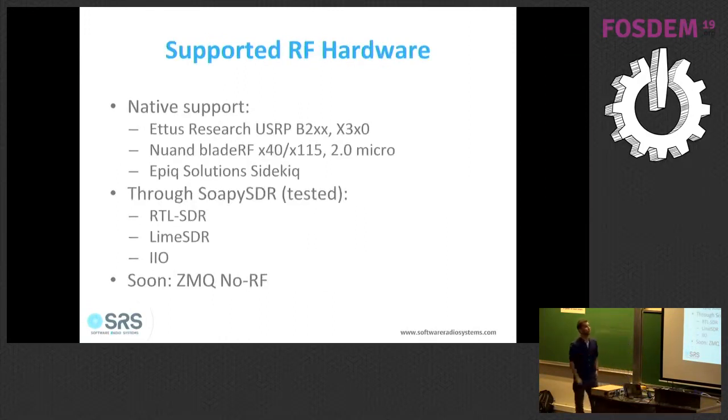Supported live hardware. So we have support for Ettus Research equipment, so basically the B200 series, the X series. We still get support questions for the N210. We don't have a resampler, so we don't support the N210. We support natively the BladeRF, the old and the new one, and Epic Solutions hardware. And through SoapySDR, those that we have tested are the RTL-SDR for receiving, Lime, and also libiio, so analog devices on embedded